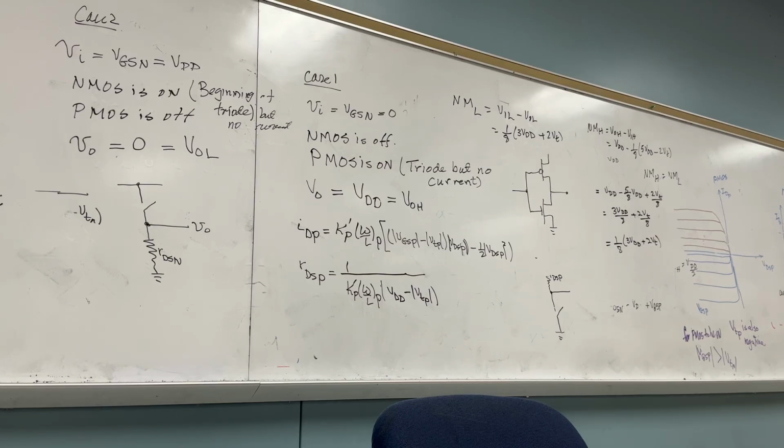That's one. Second, wiring. That's why they always tell you when you implement or design your circuit, do not use long wires. You follow me on that? You need to plan the layout very carefully such that you use as short wires as possible.